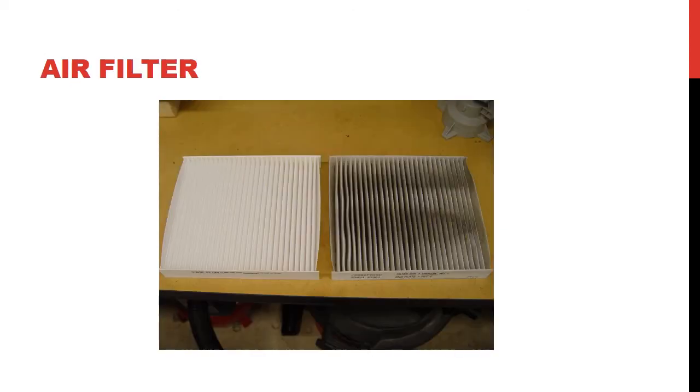Air filters. Again, one of the biggest problems with the forced hot air system is the air filter. Many times the air filter does not get changed, it gets very clogged, and the fan motor is working under overload. Eventually it will pull pieces of that filter inside because it's so old and deteriorated, and you may think that this filter is picking up stuff from the entire house. So the filter has to be cleaned. This is a dirty filter, and you replace it with a new filter.